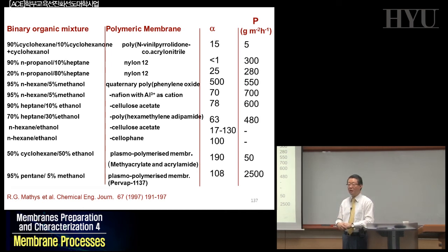But if you buy 99.9% ethanol or 99.99% ethanol, the cost will be absolutely different from your 95% ethanol because of the difficulty in separating the azeotrope aqueous ethanol. Okay? So usually when they wanted to break this distillation curve, they have to add benzene and break those azeotropes, and further distillation will eventually come with 99.9%.